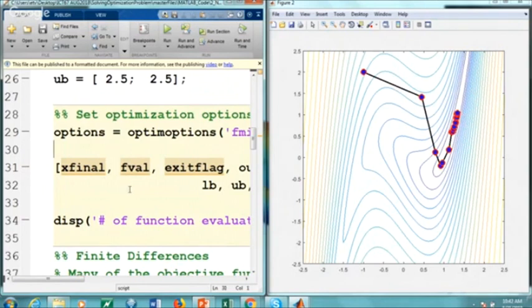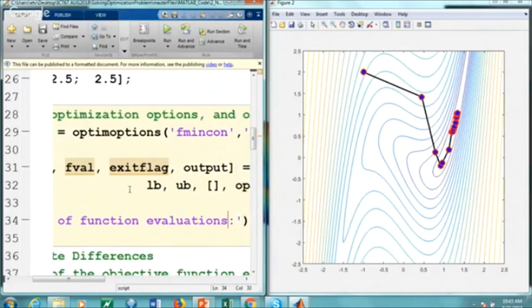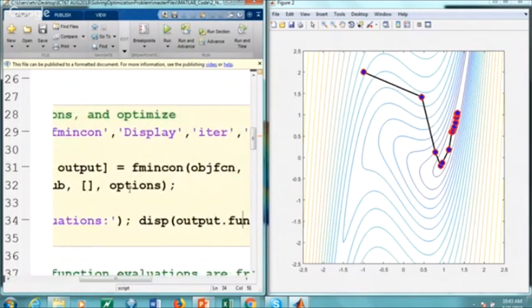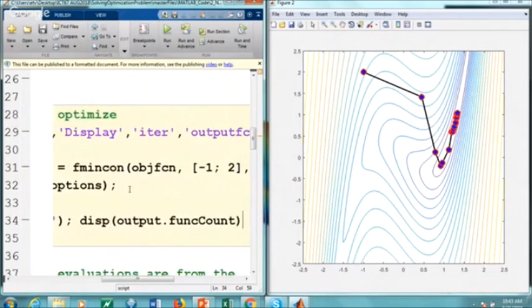So we are displaying all the happenings of that fmincon solve, and displaying the output of that function count. If you don't do it, it will just give you the final solution, but just enabling this will help you see what the function is doing.